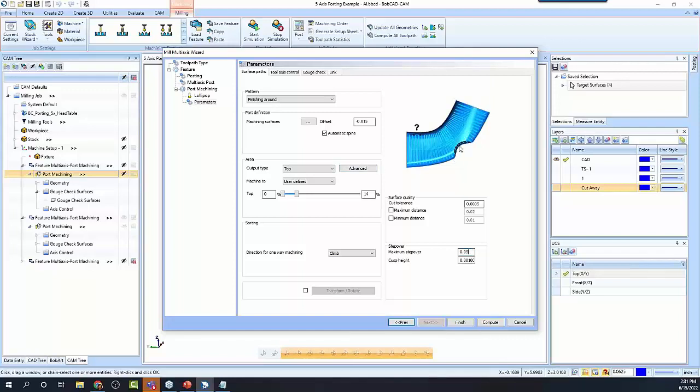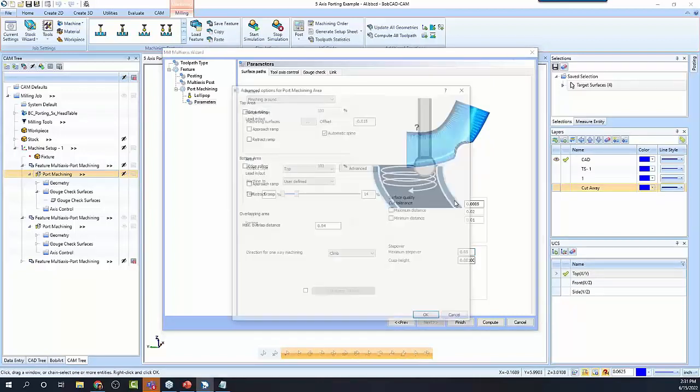If you're selecting a takeaway here, if your toolpath intersects with each other, like while it's trying to go down this down the port, if the toolpath intersects, it won't calculate or it'll stop calculation. So if you have your toolpath set up and it's not going somewhere, you may need to adjust your step over, see if it'll calculate, but it's likely that the toolpath is intersecting with each other and it doesn't allow for that.